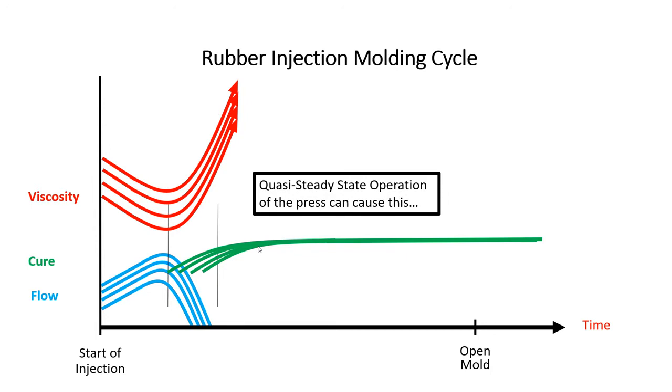But injection machines cannot do that without having a fundamental understanding. And in many cases, we can take this material characterization and load it into injection machines, very modern injection machines. And the machine itself can predict and then apply, in this case, maybe a little bit more pressure to resist against the higher viscosity, which would then stabilize the flow, which would fill the cavity in a more concise time period, which would initiate cure on a more consistent basis. And so you would have a process window that is controlled. That's the concept.